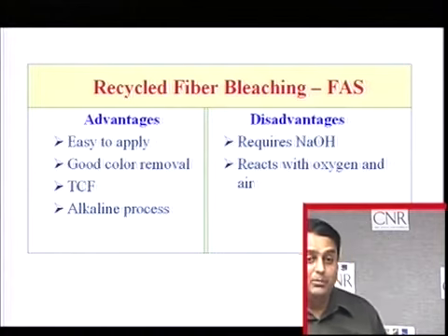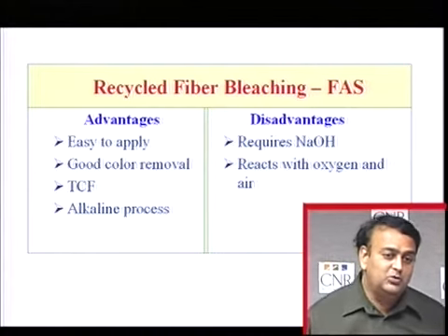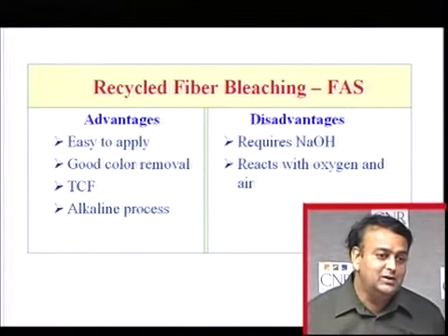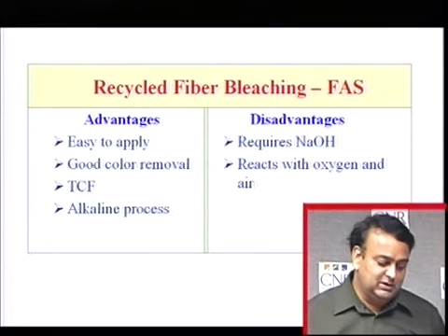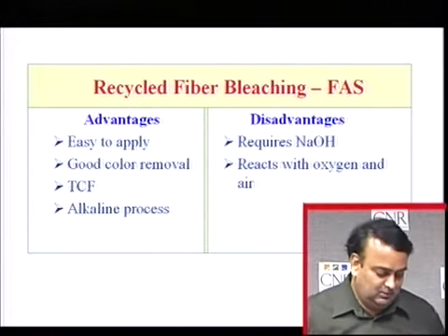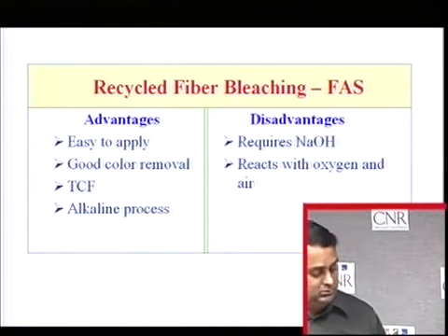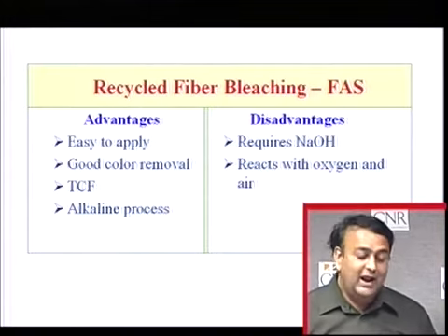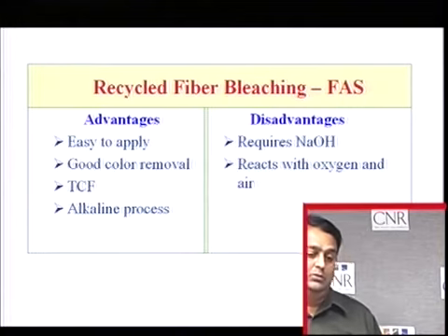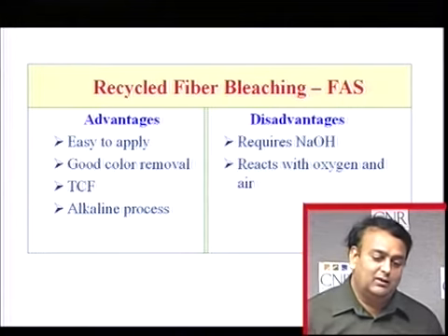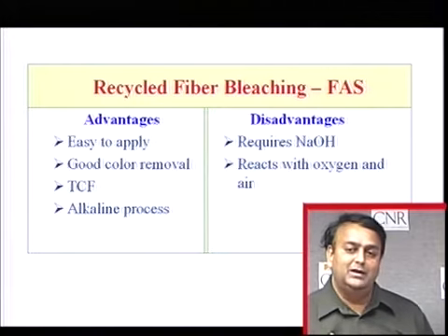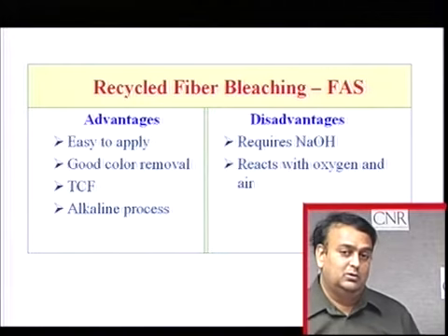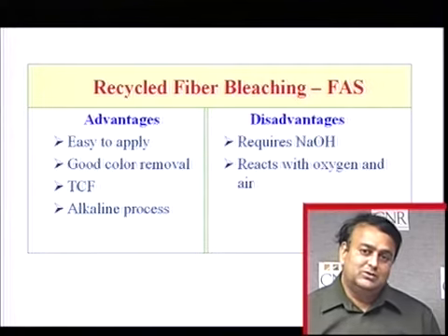Advantage, it's easy to apply. It's available in powder form. You dissolve it to form a liquid. Sometimes you dissolve it with caustic and then you pump it to the process. Excellent color removal, total chlorine free level, and it's an alkaline process. In the case of hydrosulfite, you may have to drop the pH sometimes to get the dyes out. But in the case of FAS, you need a pH of 9.